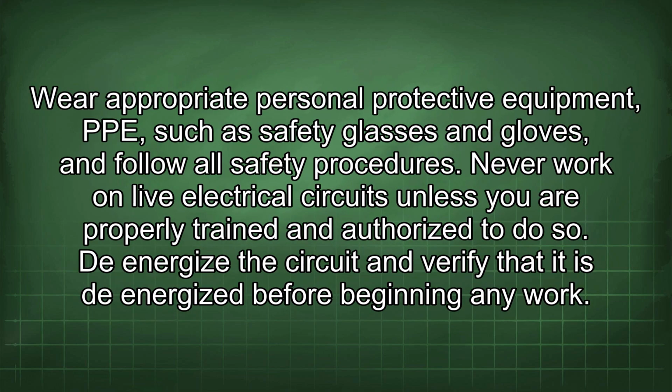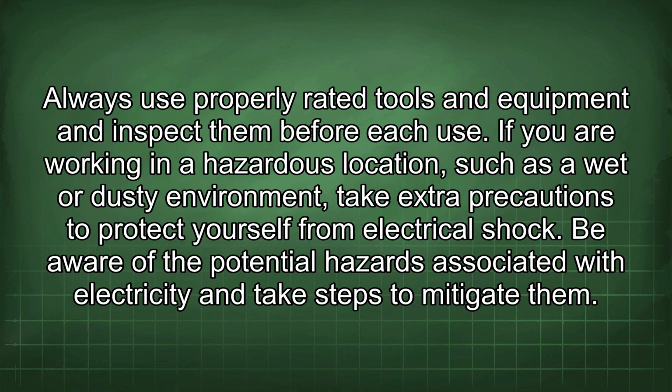Wear appropriate personal protective equipment (PPE), such as safety glasses and gloves, and follow all safety procedures. Never work on live electrical circuits unless you are properly trained and authorized to do so. De-energize the circuit and verify that it is de-energized before beginning any work. Always use properly rated tools and equipment and inspect them before each use.